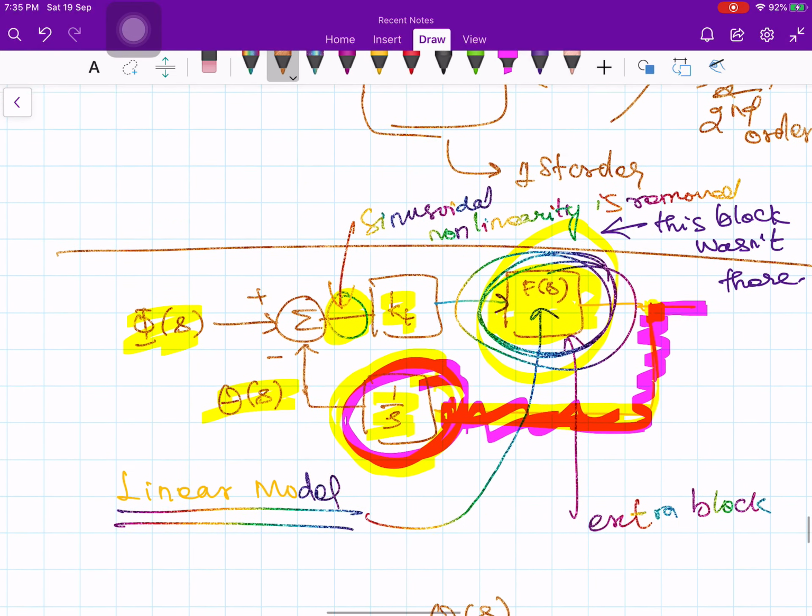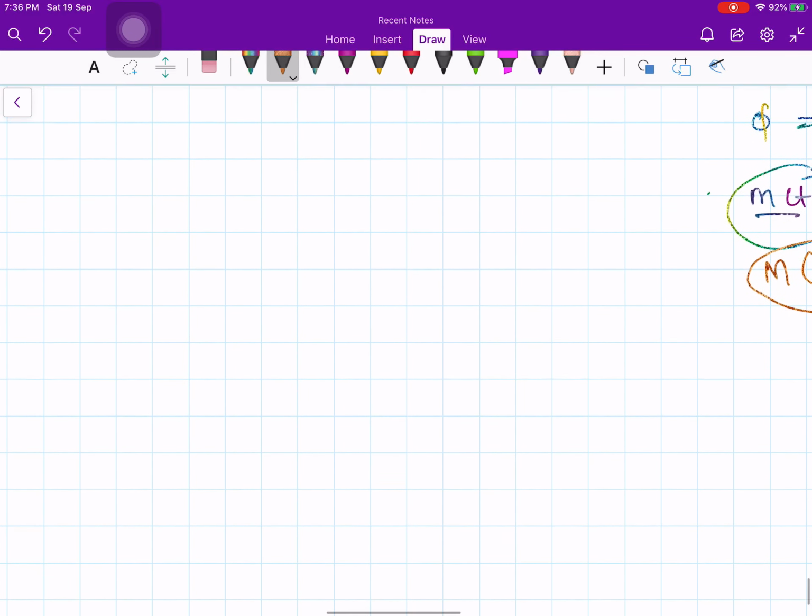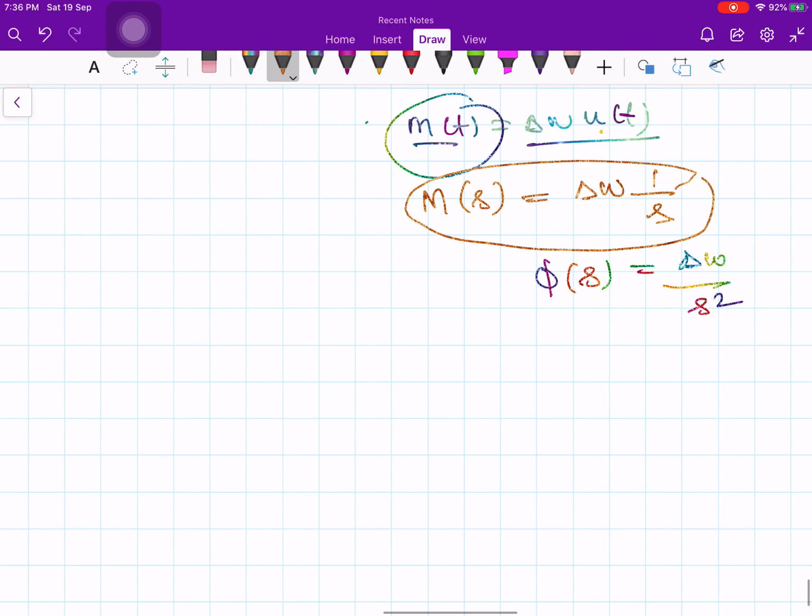So we discussed phase locked loop elaborately. One more important point: this is not the only kind of feedback demodulator. We have yet another interesting feedback demodulator, called the frequency compressive feedback demodulator. This is another very interesting variant of PLL, often used for demodulating FM signals, more or less for the same purpose that the PLL is used. It is called a system with frequency compressive feedback, and this one is similar to our phase locked loop, but there are some major differences.